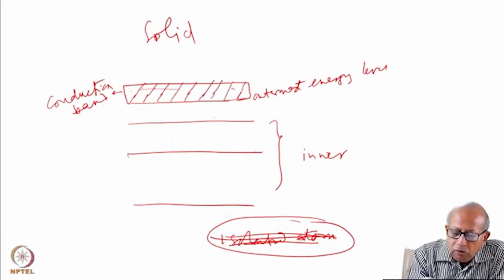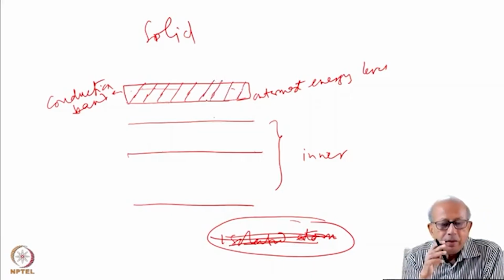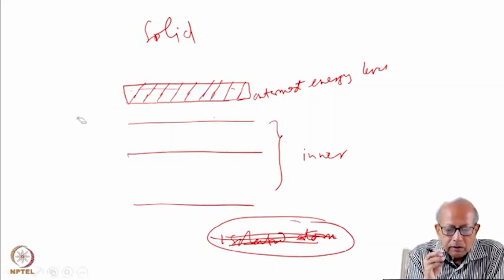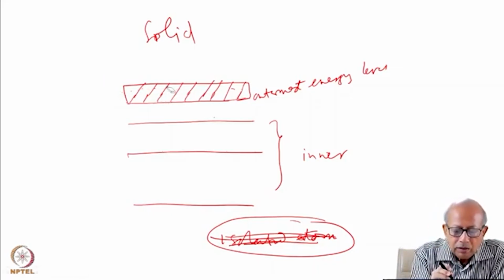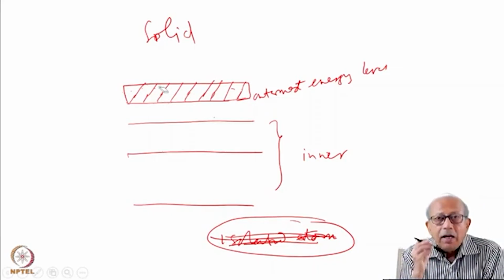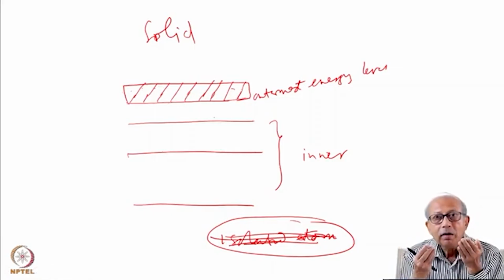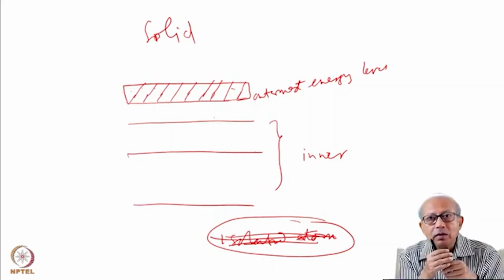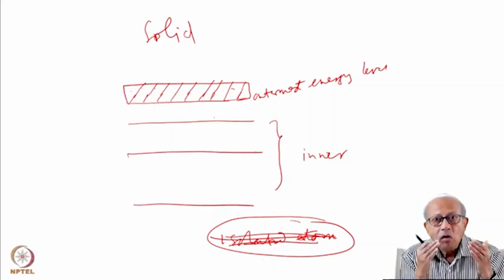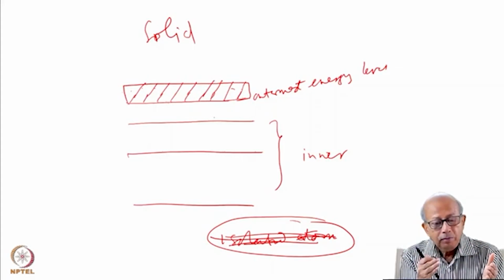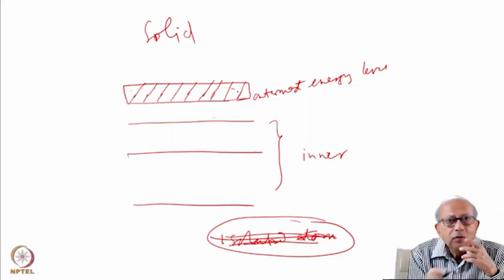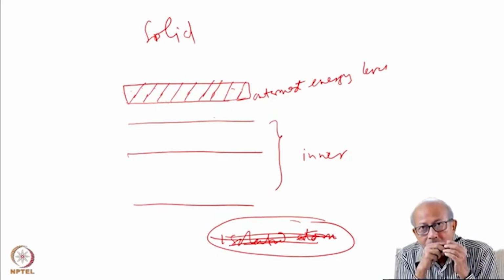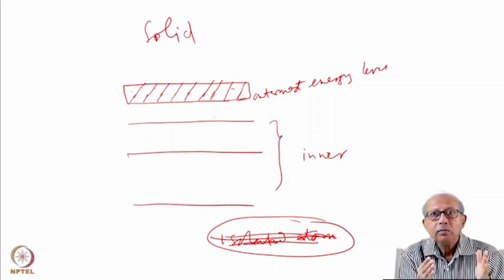And therefore, quite unlike a metal, these electrons residing here cannot acquire energy upon application of a modest voltage as in the case of a metal. They cannot conduct electricity because there is no energy space available for the electron to acquire energy and move from the applied potential difference of the electric field.